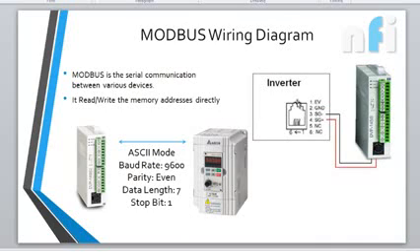So this is the wiring diagram of Modbus for a PLC. The PLC has an RS485 port at the bottom. This is a DVP14SS Delta PLC, and this is the inverter port, generally found here. If you see in the camera, it is somewhere over here. This is the port used in Modbus communication. Here, pins three and four are negative and positive. Pin three goes to the negative of the PLC, and pin four goes to the positive of the PLC. So that is the wiring.